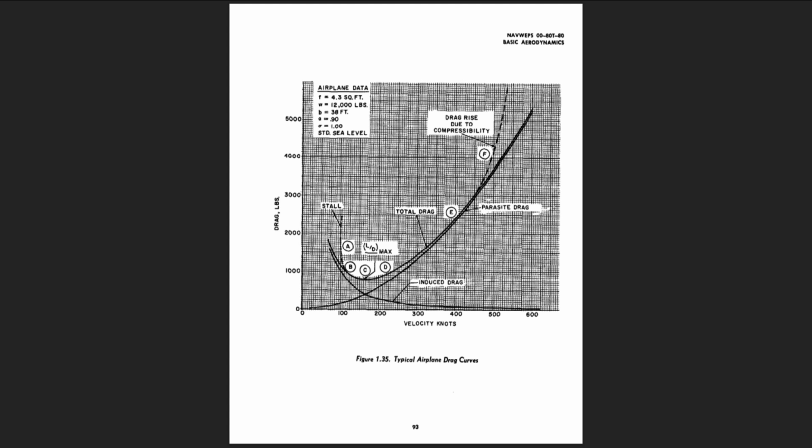C. The point of minimum total drag occurs at a speed of 163 knots. Since this speed incurs the least total drag for lift-equal-weight flight, the airplane is operating at L/D max. Because of the particular manner in which parasite and induced drags vary with speed, parasite drag directly as the speed squared, induced drag inversely as the speed squared, the minimum total drag occurs when the induced and parasite drags are equal. The speed for minimum drag is an important reference for many items of airplane performance.